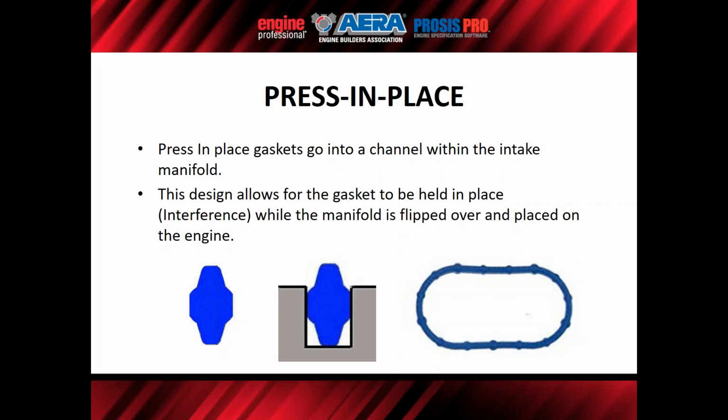So once that gasket is clamped up, if you look, this is the top of the gasket here. You've got a flange coming down that would hit the top of this gasket and compress it all the way to this surface right here on each side of the seal. Once that's clamped up, there's really a small cross-sectional area that's exposed to the air-fuel mixture. It's really like a fuel vapor that's left over.